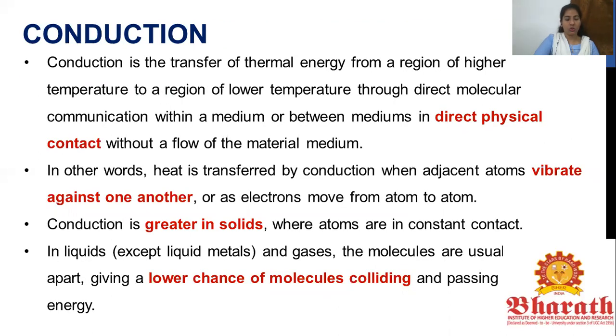So conduction. Now we'll be going into deeper topics. We'll be trying to understand all these factors and later how they affect us. Conduction is the transfer of thermal energy from a region of higher temperature to a region of lower temperature through direct molecular communication within a medium or between mediums in direct physical contact, without a flow of the material medium. The basic conduction concept requires direct physical contact, and it's a transfer of heat from a higher temperature to a lower temperature, where it has to have some kind of communication.